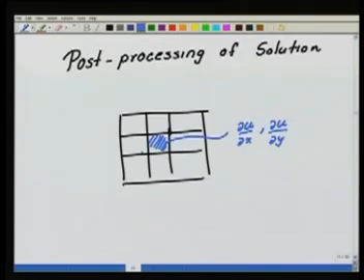How do I use my finite element data to get a better value of these things, that is better with respect to the exact solution? Because the finite element solution as such will have jumps in these quantities at the interface boundaries, while the exact one is nice and smooth. So what we would like to do is obtain a better information about this data at this point.